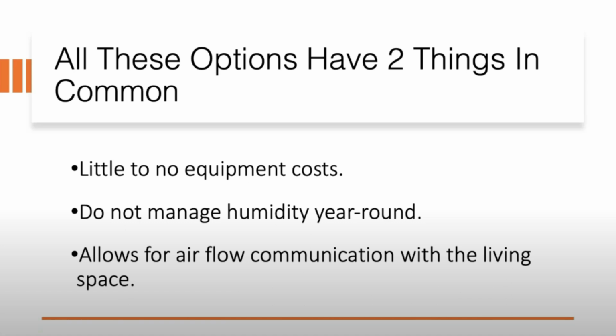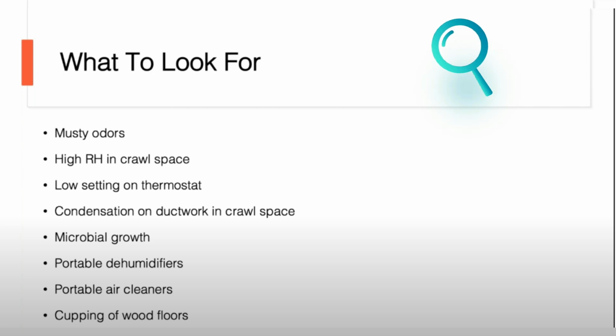Because this allows communication between the crawl space and living space, those of you in the pest industry dealing with termites know that at times there will be chemicals that have to be used in the crawl space. Typically, you would not want those chemicals being pulled in or shared with the living space. Things to look for in a crawl space include musty odors.